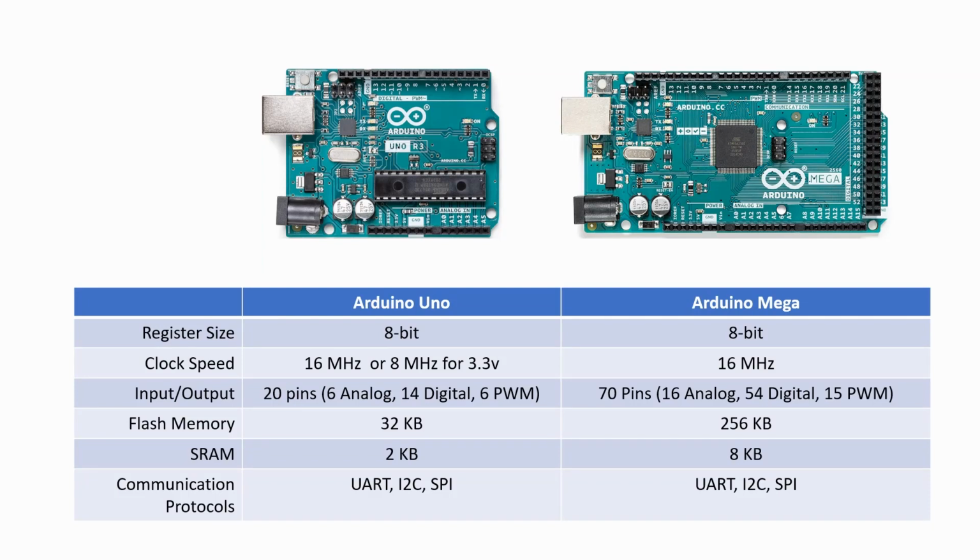However, before I begin with the STM32, let's start with something more familiar, the Arduino platform. The Arduino is based off the 8-bit AVR microcontrollers produced by Atmel. It's really gained popularity due to its simplicity and easy to use IDE. However, it lacks capabilities that we're interested in for real-time digital signal processing. It has a very slow main processor clock frequency. It's got limited memory and I/O. It's got very simple ADCs that don't allow us to do any kind of high frequency sampling, and it lacks a debugger. So for real-time digital signal processing or control systems, this is not what we want to use.